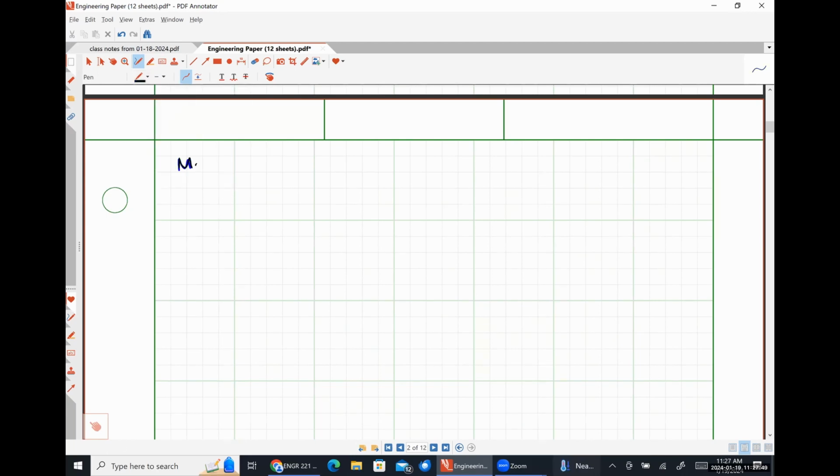So now we're going to talk about MOSFET characteristics. All of this analysis is going to be from the perspective of us looking at an NMOS device, much like we looked at an NPN device or NPN BJTs, figured out how all that works, and then we're like, okay, well, PNP kind of works the same, but we flip the letters. It's going to be pretty similar to that. Okay. So the first thing that we're going to talk about is the threshold voltage.